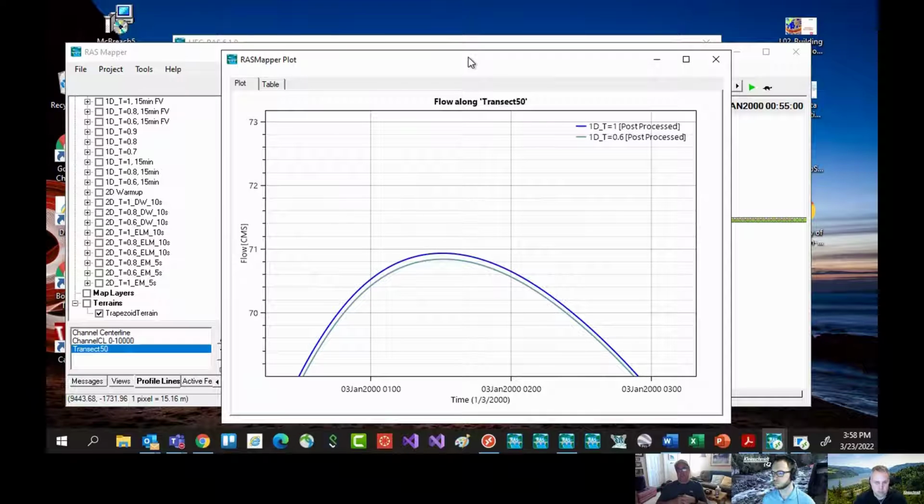So in other words, if we had used a larger cross-section spacing and a larger time step, we might have had some numerical diffusion we didn't even know about, right? Yeah. But then if we just did the theta test only, we would probably see even bigger differences because of theta also at this point. So shorter or closer spaced cross sections and closer spaced cell centers is a good thing to work towards here. But along with that, you've got to have a correct time step too,